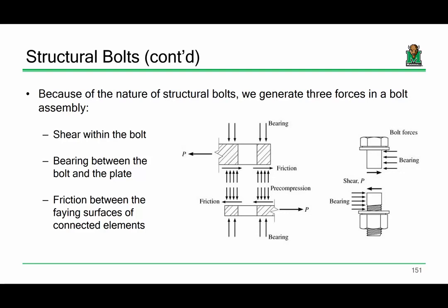Well, I'm just indicating that there's tension, that there's friction between those 2 plates. I just separated them so you can see it. So there's friction, and then there's pre-compression. So think about it like this. You have a plate A, plate B, you stick a bolt through it, and you start tightening it. What happens to the plates? They compress together. And if they compress together and develop a normal force between the 2 plates, you got friction. That's a good question. Everybody else?